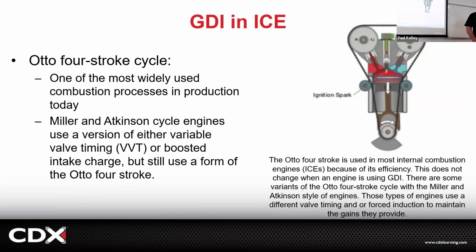So in the day, the 4-stroke cycle, just remember intake, right? On the intake stroke, the intake valve opens and we would suck in air and fuel because we sprayed the fuel way back here. The air and the fuel would go past the valve, and maybe a little bit of droplets would get stuck in the intake port, maybe on the valve, and a little bit of droplets might land on the cylinder. Those droplets are lost power and lost fuel economy. You understand? And increased emissions.